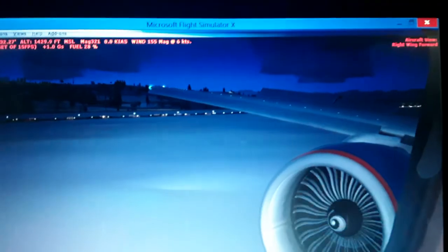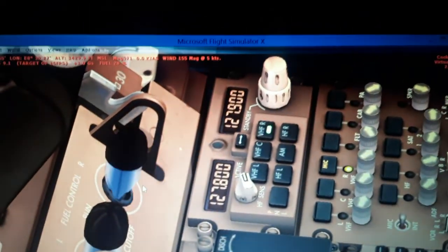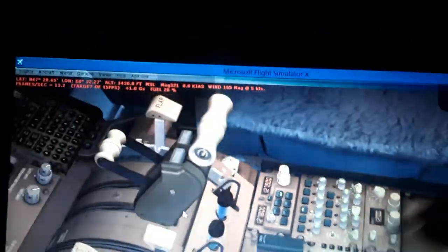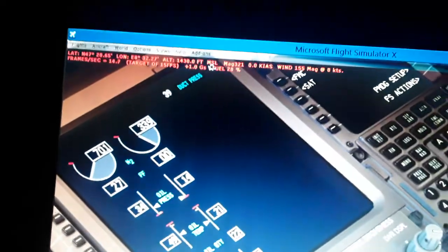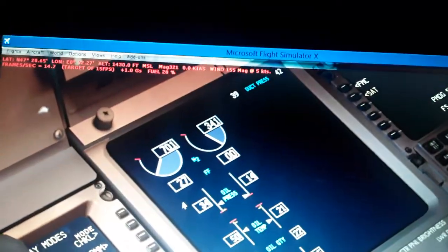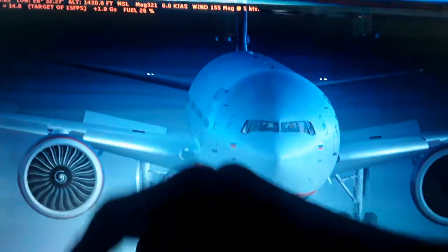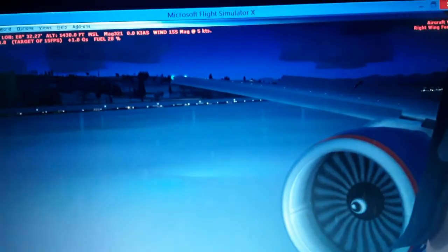You see the engine spinning faster, so we can start the right wing and the fuel flow valves on. You will see the fuel flow increase from 0 all the way up for the right wing engine. So here we have the right wing engine start also, start spinning. And here we go. We have both engines running normally.